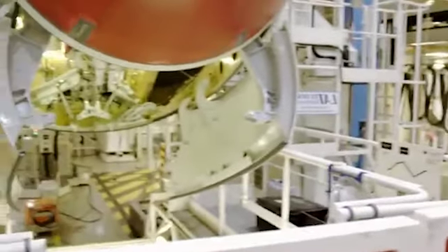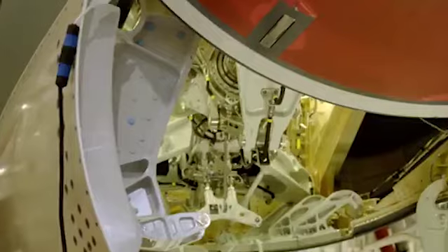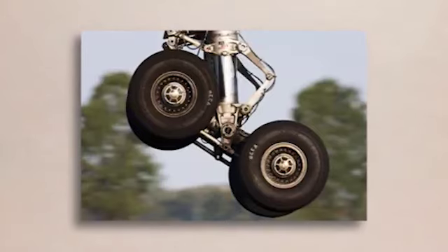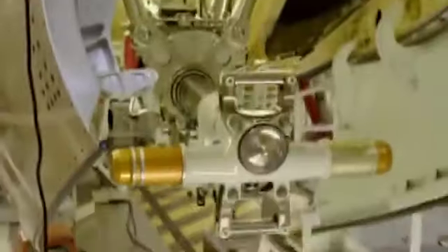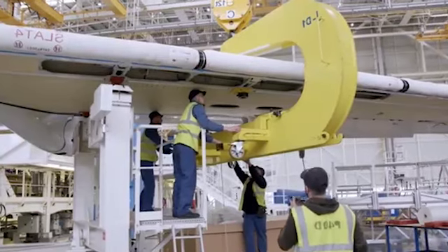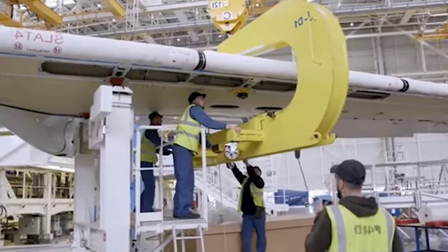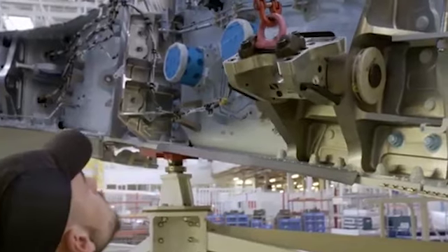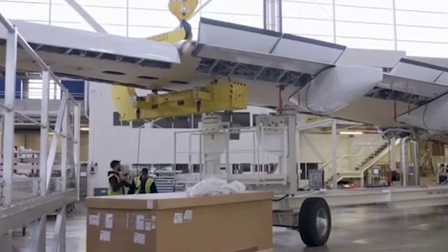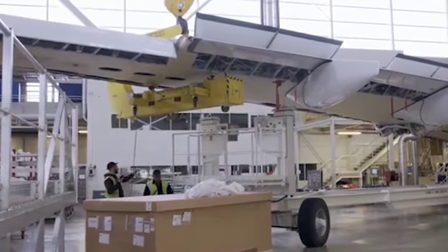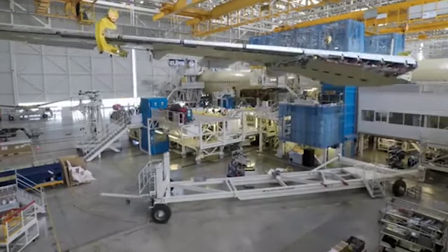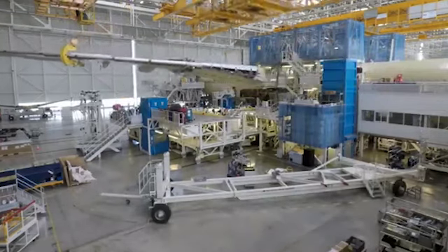The manufacturing process involves the creation of various components such as the fuselage, wings, engines, and landing gear. The manufacturing process for each component differs depending on the material used and the component's design. For example, the wings may be created using a process called extrusion, where long pieces of aluminum are formed into the desired shape, or they may be constructed using carbon fiber composites, which are layered and cured in a mold.